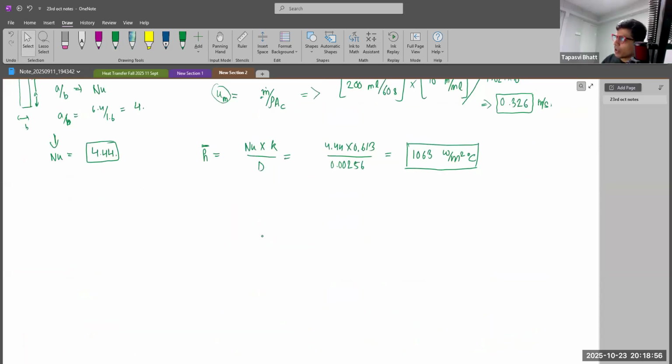So I'm going to say m. Basically, the area of the surface for the second part of that equation is the perimeter times the length, right? What is the perimeter of the tube? It is 2 times (6.4 plus 1.6) times 10 to the power minus 3 times L, which is 1.6 times 10 to the power minus 2 L. This is the area of the surface.